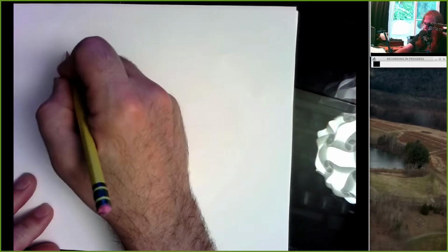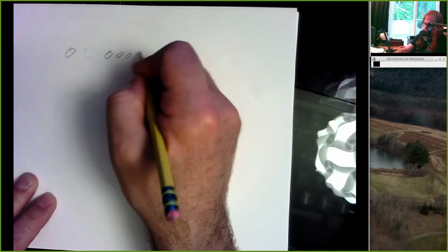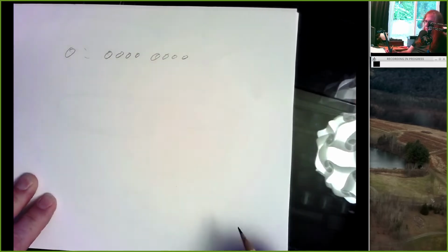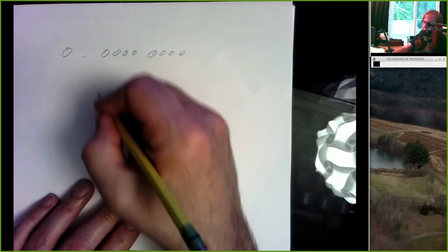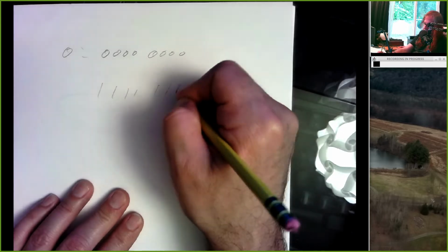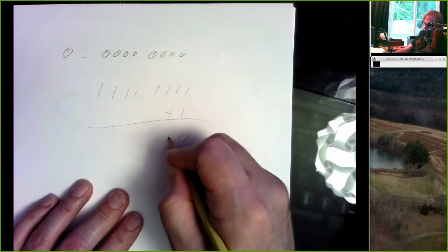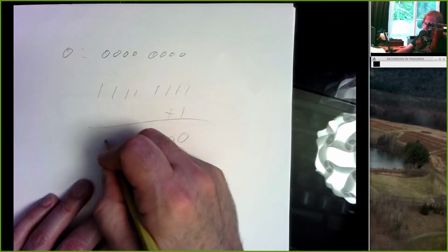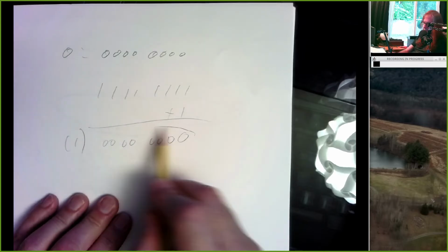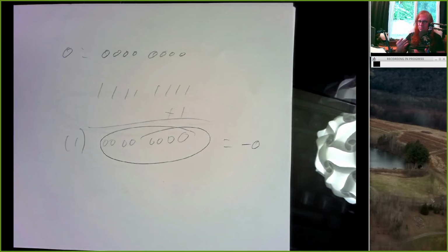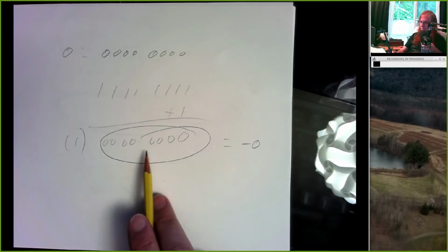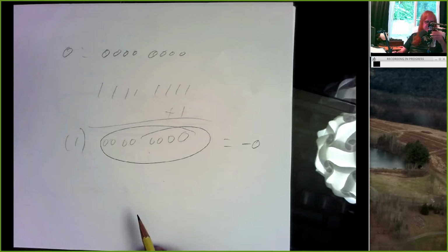But if we have something like, 0, and you want to find the expression in 2's complement for the negative of this, well, toggle all the bits and add 1, and you're going to ripple that final carry all the way over. That's how you represent negative 0, which in a reasonable world should look the same as positive 0. So that's one number that's both positive and negative.